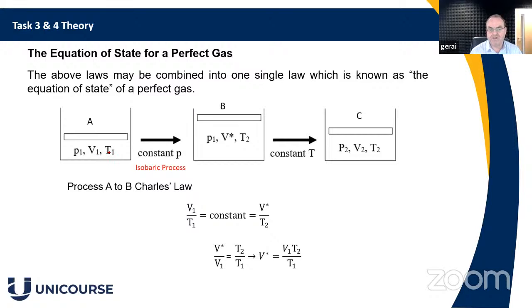As the temperature increases, the volume will increase, because this piston isn't constrained in any way. It's allowed to move up, with air pressure on the outside applying a steady force downwards, so the gas is able to expand in volume and increase in temperature, but the pressure will remain constant because the force acting down is the same in A as it is in B.